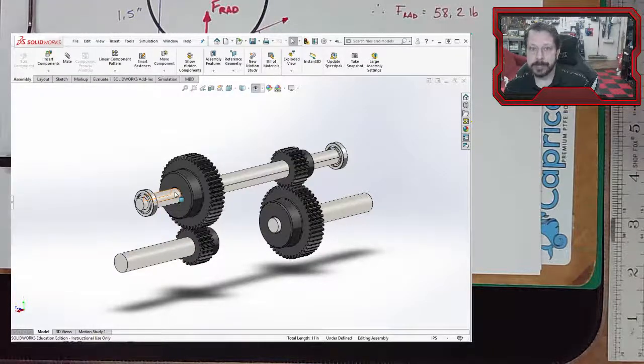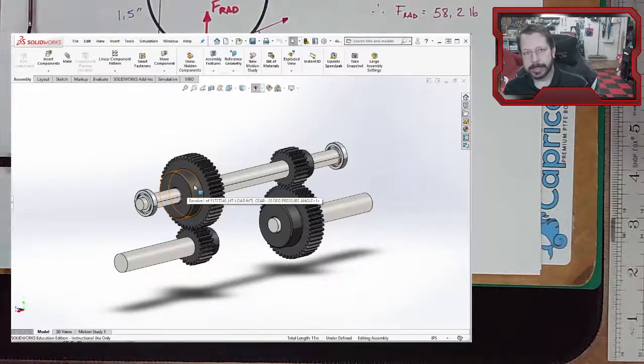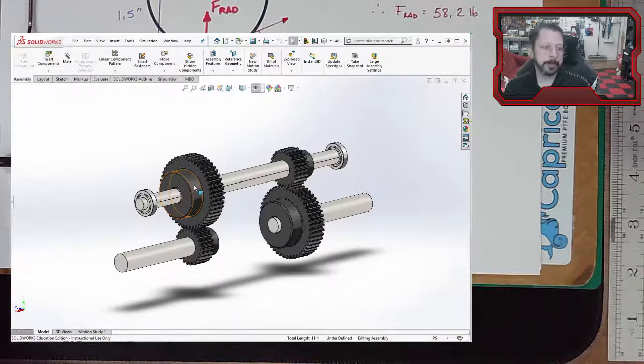You would do the shear and bending diagrams to calculate the bending moment at the point to calculate the stress. But you would do just a superimposed two-point load, in this case, on a beam to figure out the deflection. If it was okay with being just the thin part, then it's certainly okay if it's thicker somewhere. So you could do it that way by hand.